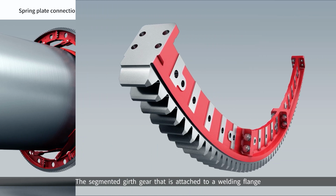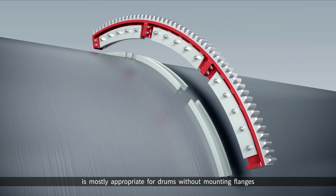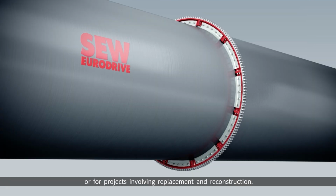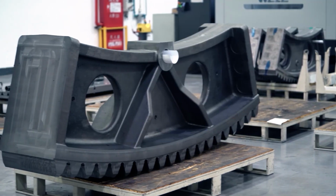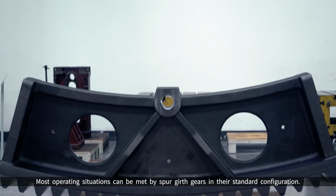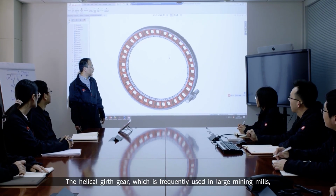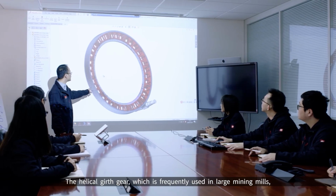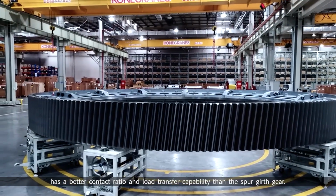The segmented girth gear that is attached to a welding flange is mostly appropriate for drums without mounting flanges or for projects involving replacement and reconstruction. Most operating situations can be met by spur girth gears in their standard configuration. The helical girth gear, which is frequently used in large mining mills, has a better contact ratio and load transfer capability than the spur girth gear.